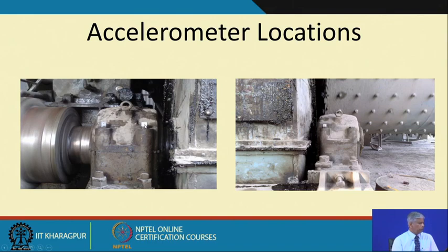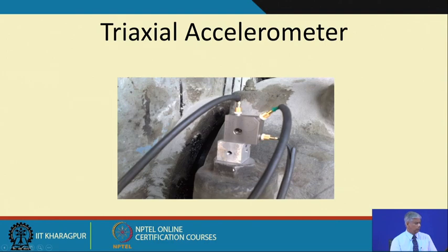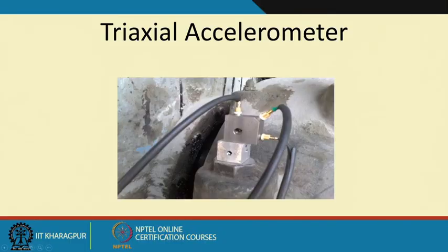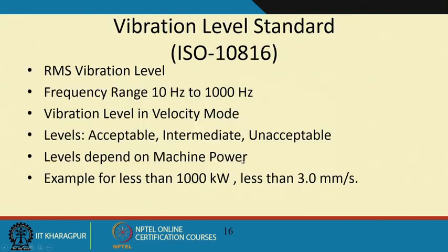So, usually I put a pre-tapped block of aluminum on, glue it there, and then mount my accelerometers for measurements. This is the bolt head onto which I have glued my block, onto which I have screwed this triaxial accelerometer. This is a good practice to have in your kit when you are doing vibration based measurements: carry some of these mounting blocks with you. They are very easy to make, but you have to make sure that the surfaces are nicely machined.